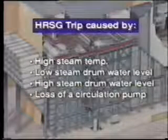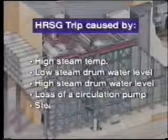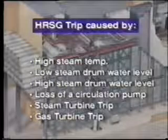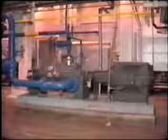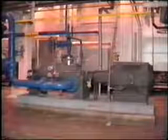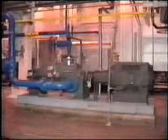Loss of a circulation pump in a forced circulation HRSG. A steam turbine trip with consequent fall in steam demand to zero. A gas turbine trip. What would happen to the condensate and feed water pumps in the case of an HRSG trip? Well, these would continue operating, supplying water as necessary.